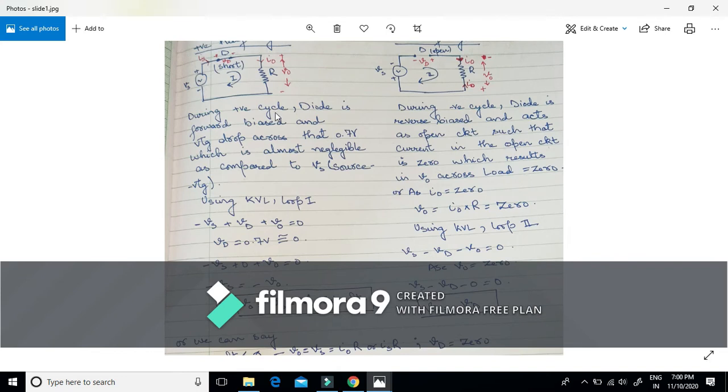The voltage across the load, V naught, is equal to Vm sine of omega t. Moreover, as already explained, we are using an ideal diode. The voltage drop during its short is 0.7 volt, but that's almost negligible as compared to source voltage. That means the voltage across the diode is 0.